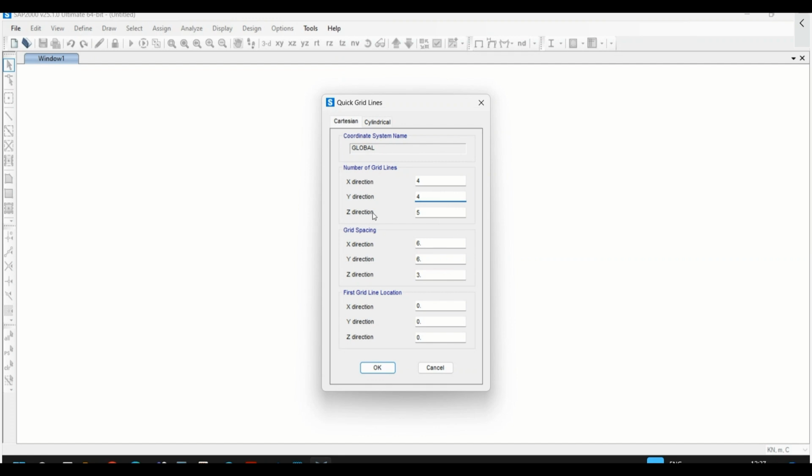So here, unlike ETABS, you'll have the grid system defined simply based on the x, y, and z axes. In ETABS, you had x and y, and then along the z direction, you had stories. Number of stacks of stories, you can call it like a 10-story building, a 50-story building. So you have story idealization in ETABS. Here we have no such idealization. It is purely based on the grid lines, based on the coordinates, the global coordinate system. So global coordinates are x, y, z,